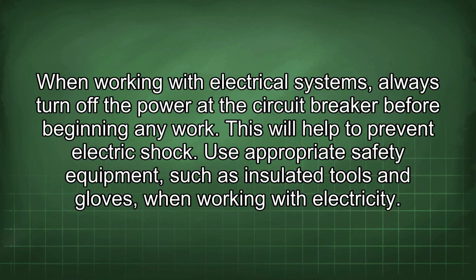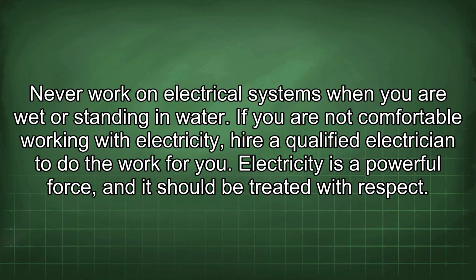When working with electrical systems, always turn off the power at the circuit breaker before beginning any work. This will help to prevent electric shock. Use appropriate safety equipment, such as insulated tools and gloves, when working with electricity. Never work on electrical systems when you are wet or standing in water. If you are not comfortable working with electricity, hire a qualified electrician to do the work for you.